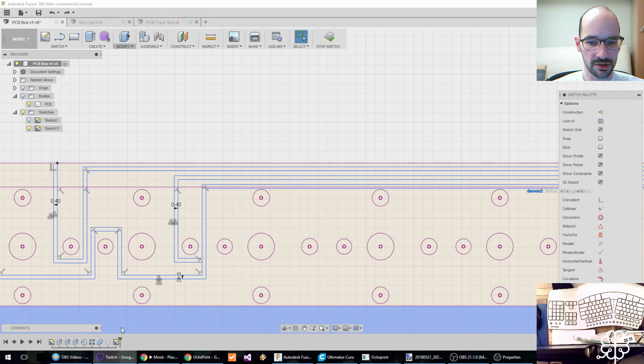Making the pins longer means soldering something to the pins, which means I have to solder. If I solder something to the pins, I'm just going to make it point-to-point wiring. I'm basically just going to put the switches in the plastic and solder a wire to all the legs that it needs to go to, and just be done with it. But I was trying to avoid that because it's kind of labor-intensive, and it means it's more painful for other people to replicate this process later on.